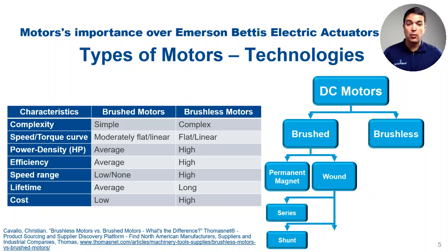Speed control is available on separately excited motors. A vacuum cleaner is a simple example. The last type is the compound type, which is a mix of both types mentioned before. It provides better starting torque and speed regulation. These motors are used inside a circular saw.